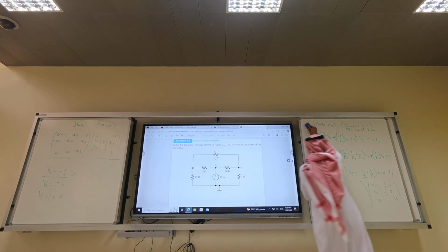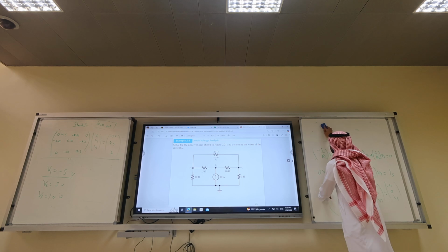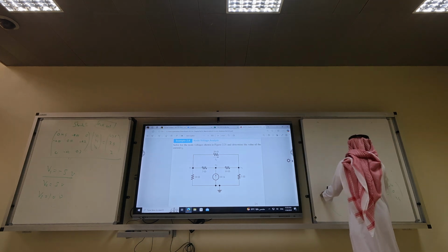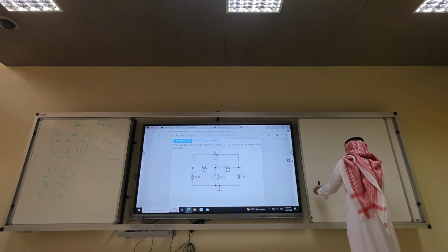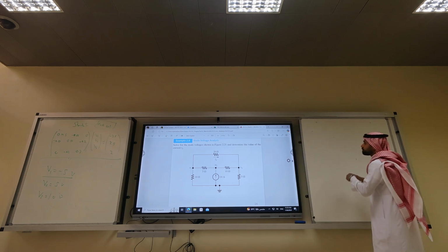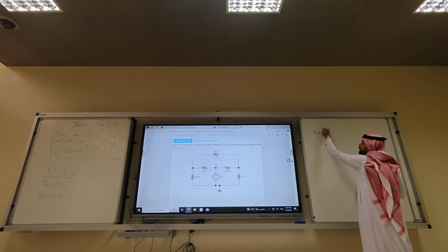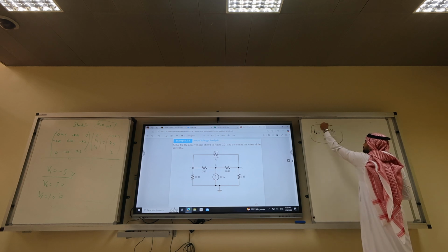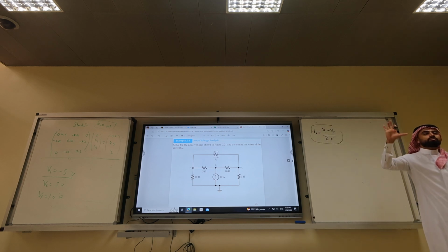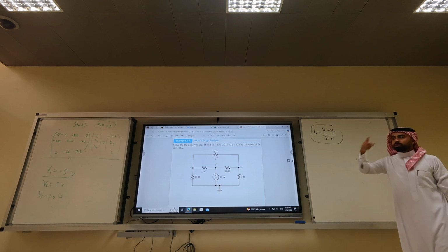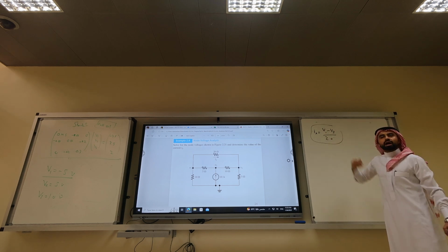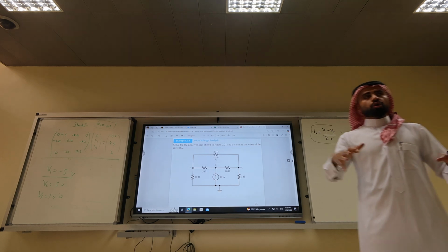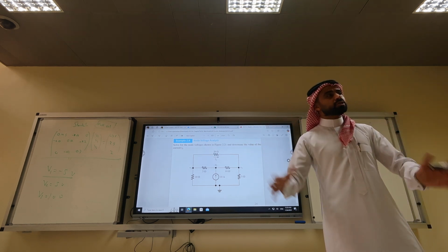Why? Because we know the key of nodal voltage analysis is that Ix equals what? Ix equals V1 minus V3 over 20. So if I know V1 and V3 in the nodal voltage analysis, and this is a common trick, they give you one unknown, they're expecting you to find V1 and V3 along the way. And as a general advice, in power systems or electrical engineering, if you know the voltages, you know everything.